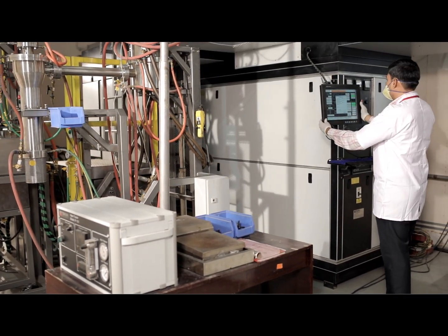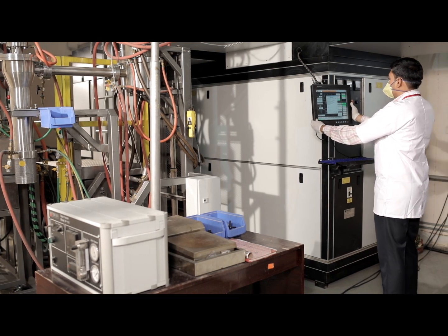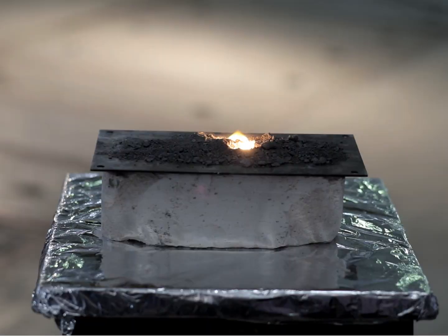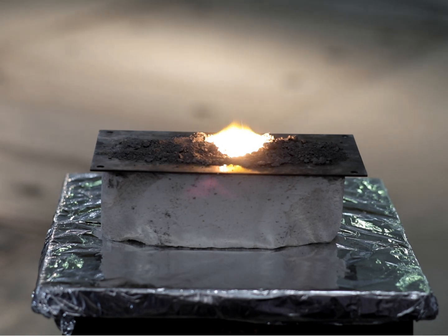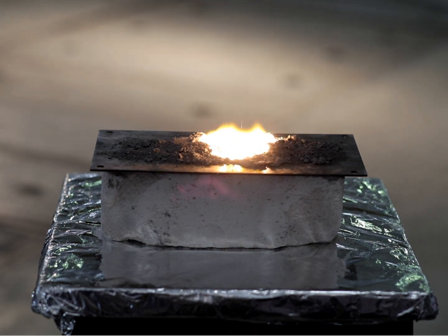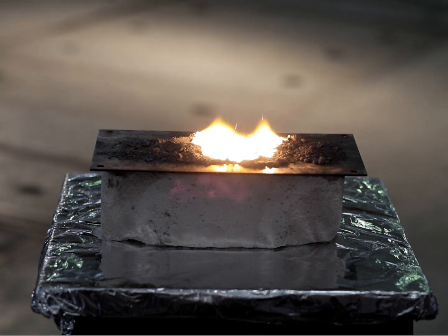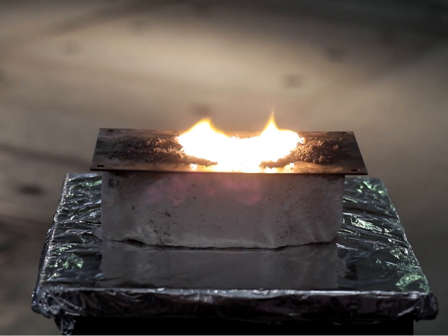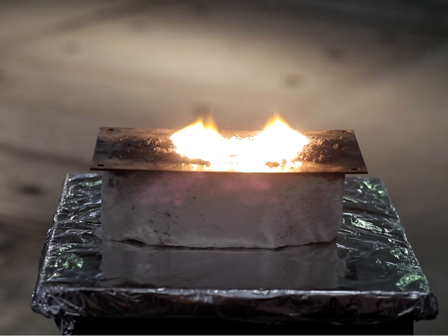The flow of quenching gas converts this vapor into nanoparticles, which are collected in the glove box. Ultrafine, metallic, aluminium nanopowder produced in RF induction plasma plant has shown very high burning rate due to its enormous surface energy. The ignition efficiency of rocket propellant is tremendously increased by adding small quantity of nano-aluminium powder to it.